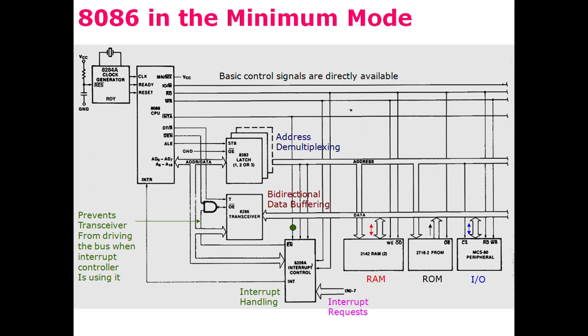The address and data multiplexed pins are connected with latches to demultiplex address and data from each other, and this would give us the address bus.